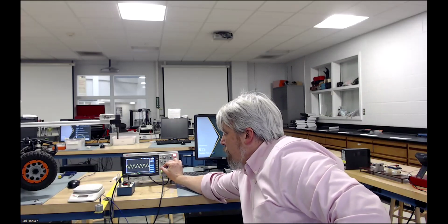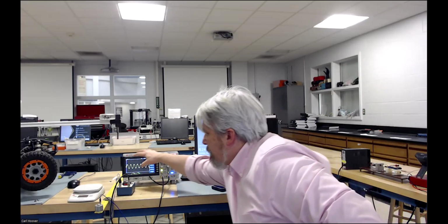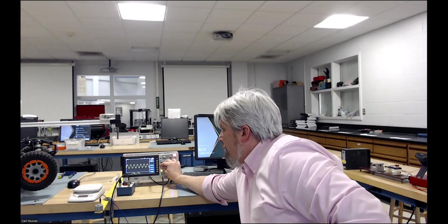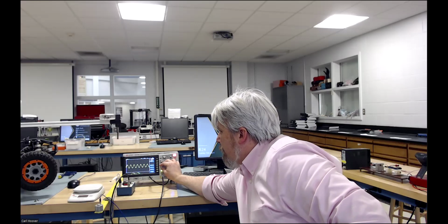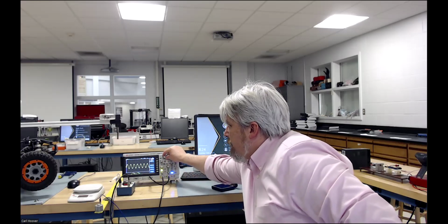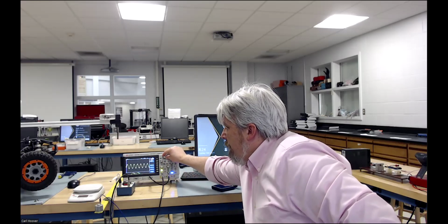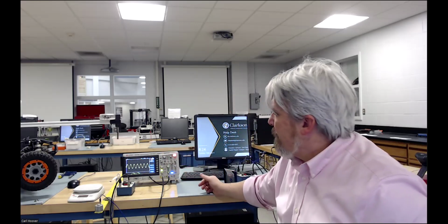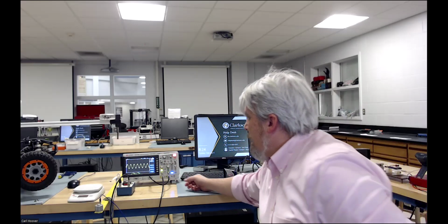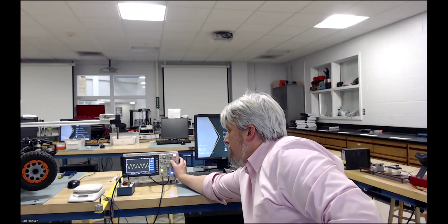If I change this voltage knob, more volts per division, it's the same waveform, it just looks bigger, and you can actually see up top here where it shows the number of volts per division. And I can also do the same for capturing the time at different time divisions as well. I can use the cursor functionality,